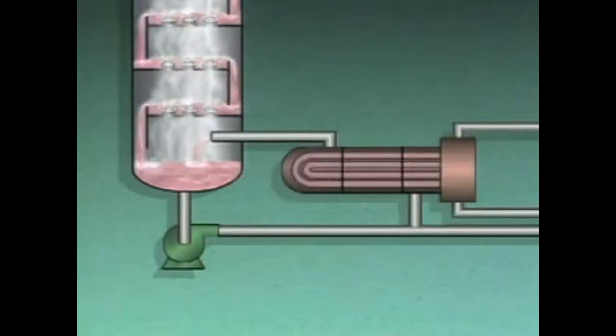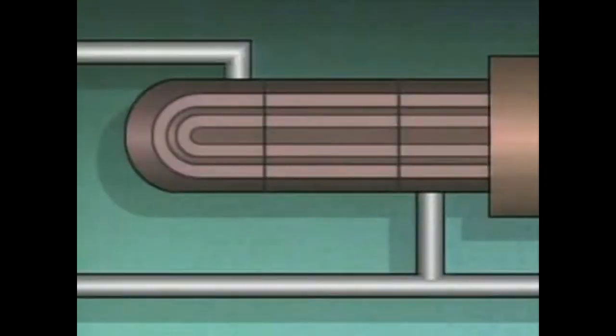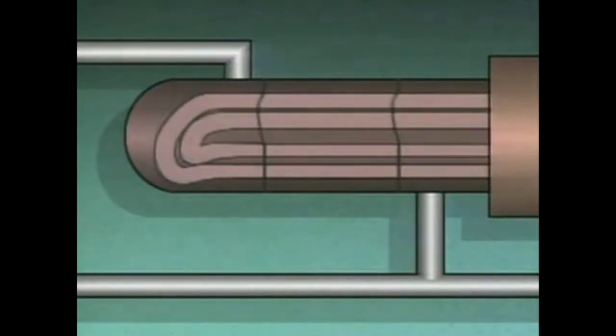Once the reboiler is ready to receive steam, the steam should be supplied gradually. If steam is supplied too quickly, the tubes in the reboiler could expand unevenly and possibly crack. If the column pressure is greater than the pressure in the steam system, some of the mixture could contaminate the steam system and damage it. If the column pressure is less than the pressure in the steam system, steam could leak out and contaminate the mixture flowing back to the column.